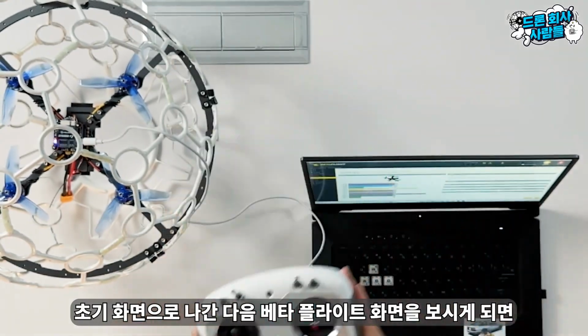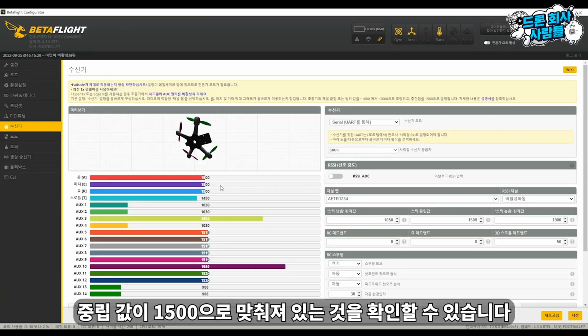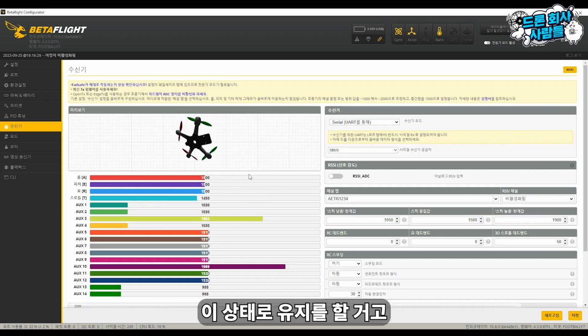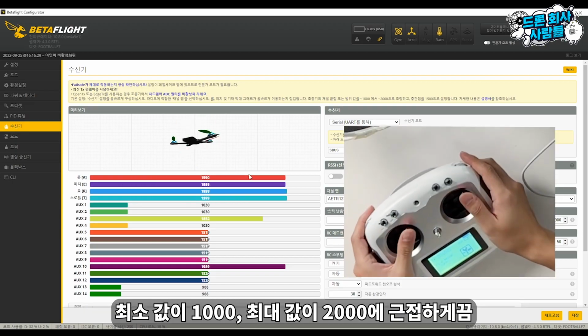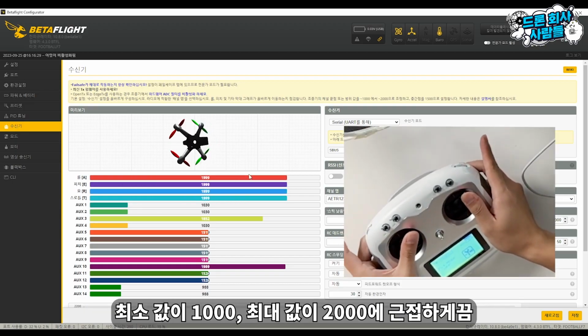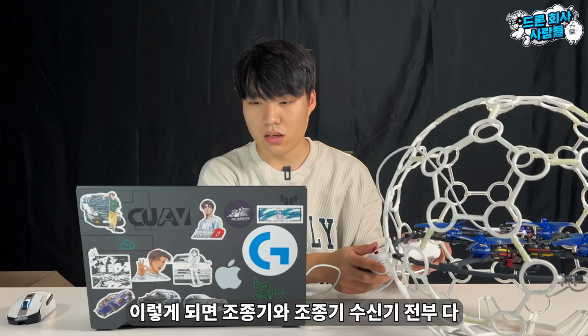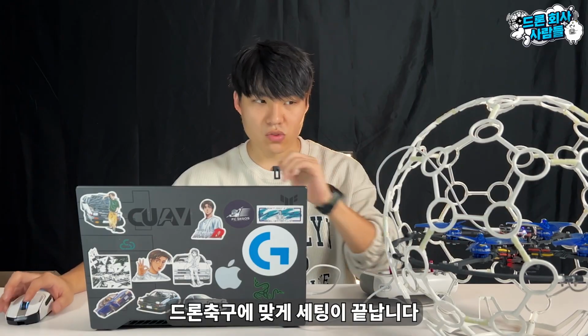Now, when you look at the Betaflight screen, you can confirm that the neutral value is set to 1500. The throttle value not matching the neutral value is not a significant issue, so it will be maintained in this state. On the Betaflight screen, you can see that the minimum value is set close to 1000, and the maximum value is set close to 2000. With this, the setup for both the transmitter and receiver for drone soccer is complete.